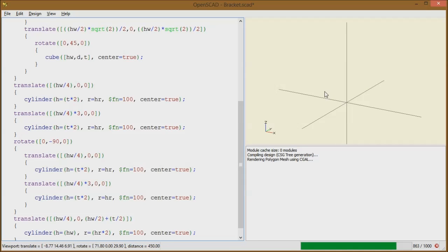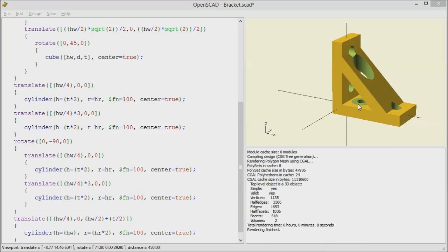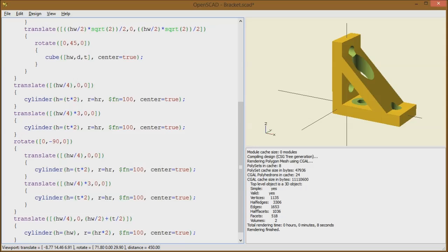sorry, rendering sometimes takes a while once you're getting a lot of detail on the model, which is exactly one of the reasons I think it's dangerous to do large systems in SketchUp, because it just eventually gets so slow that it's not usable. So what you'll see now is that rendered correctly, but that little bit is green. The reason for that is what I mentioned last time, where your cut surface and your model surface are sharing a surface there. So you could give this a go and it'll probably work, but I just feel slightly uncertain there. I'd like to be a bit surer.